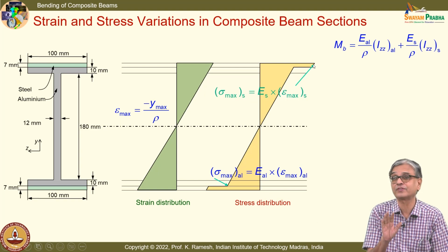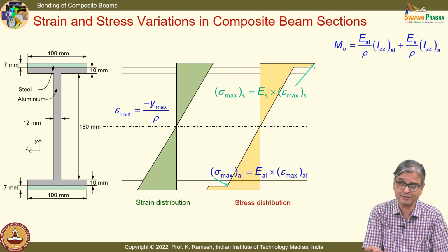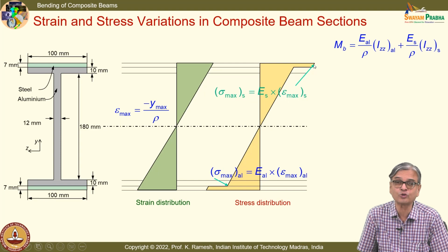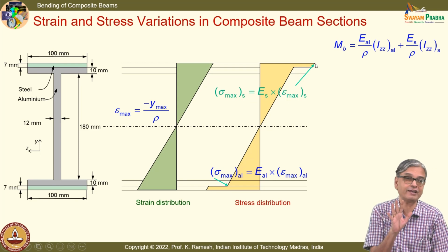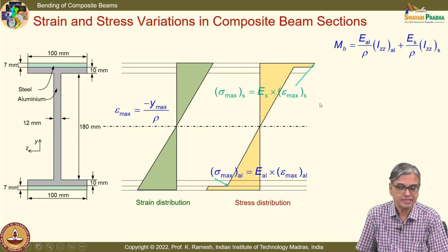That is the importance of what happens in a bending situation. In the case of a composite hoop, we had similar thicknesses of the hoops. They are not very thin compared to this. But the way the hoop is constructed, the way the hoop is resisting the load, it is going to have a constant stress in the outer hoop and constant stress in the inner hoop. Whereas here, even though the thickness is only 7 millimeters, because this is resisting bending, from our basic expression, this stress will vary linearly over the small depth. So, you have to recognize these subtleties. Is the idea clear? The focus of this problem is to appreciate that strain variation will be linear, whereas stress variation can have a jump.